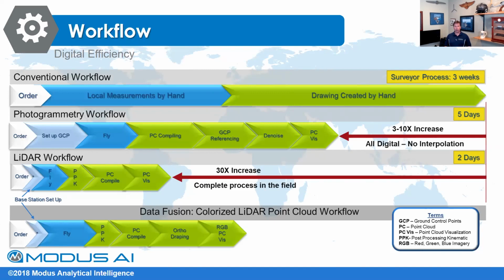Now, what we're going to add on to that example is what I see on a typical day when I'm using LiDAR. And I've actually been very conservative with the numbers that I deal with. But typically, let's say I'm doing 15 acres. A really good example, I was doing a couple months ago, I did a rock quarry. I was using just a VLP-16 and a DJI drone. I cleared 15 acres in 22 minutes. It took me 30 minutes to set up, get my base station and all that running.